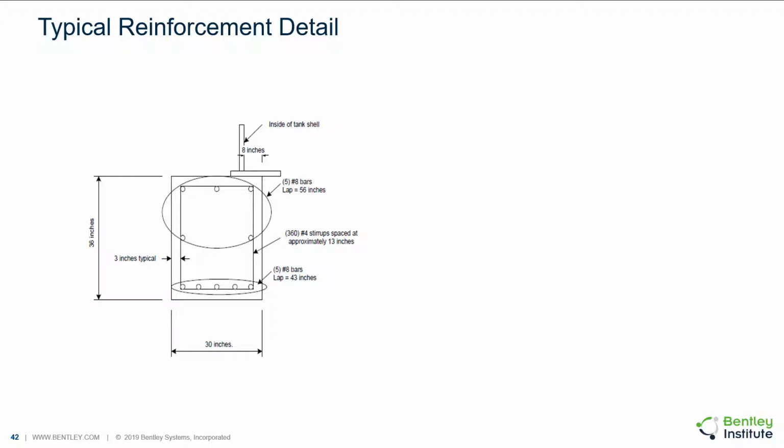Ring wall should be minimum 12 inches wide and minimum 3 feet in height, 12 inches of that being above the grade and 24 inches below the grade. These are of course minimums, and your actual dimensions could be larger.